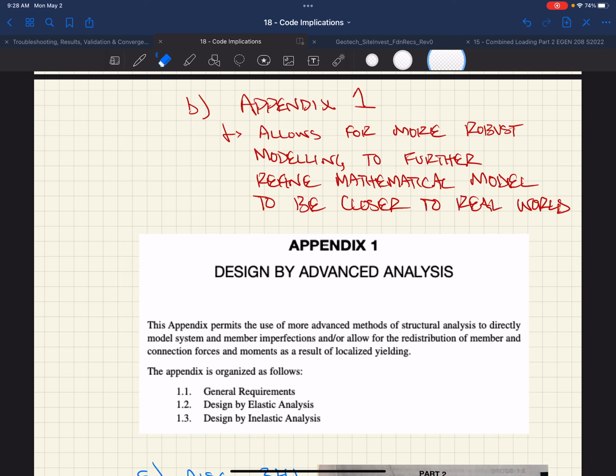If you really want to sharpen the pencil, and in some cases, when you do a big high rise and they do experimental designs, like there were some big ones on the western seaboard where they started doing this composite construction with concrete and steel, where they essentially used the steel as the formwork and had a bunch of headed anchor studs in it, and then you cast concrete, and that's the concrete core.